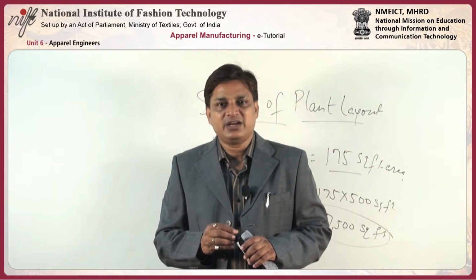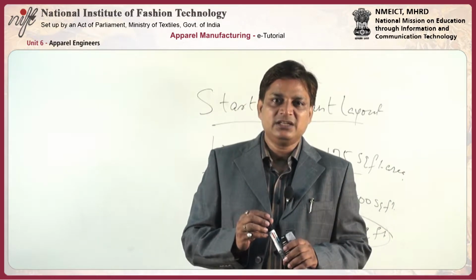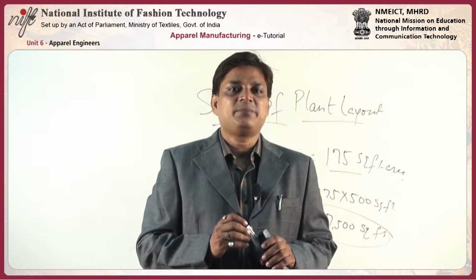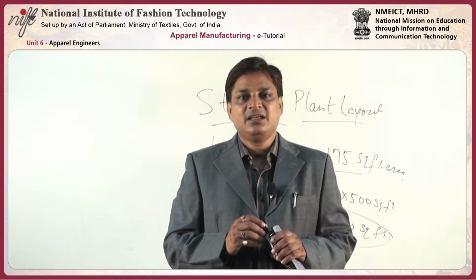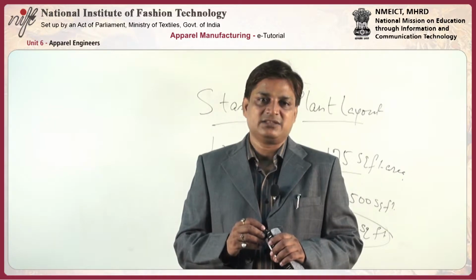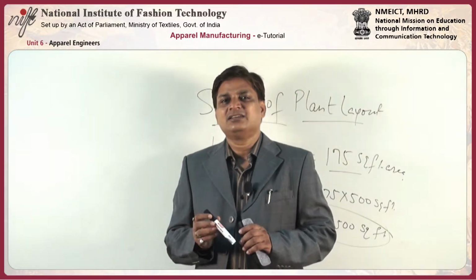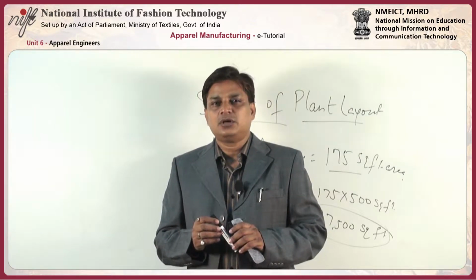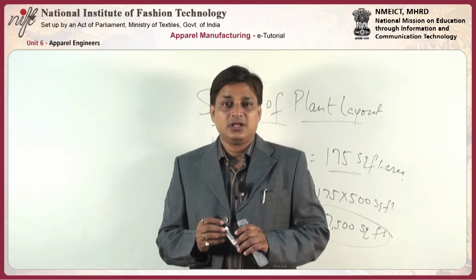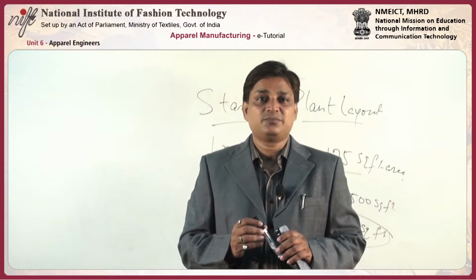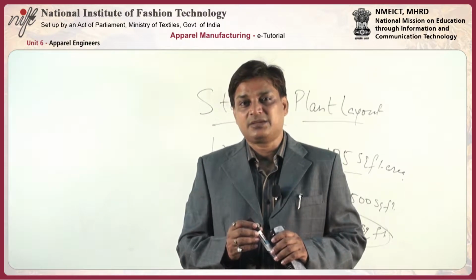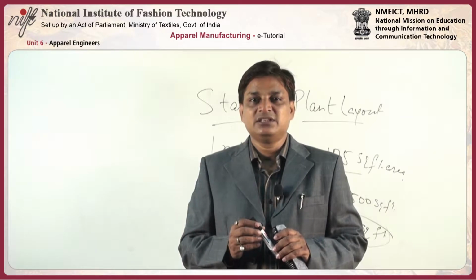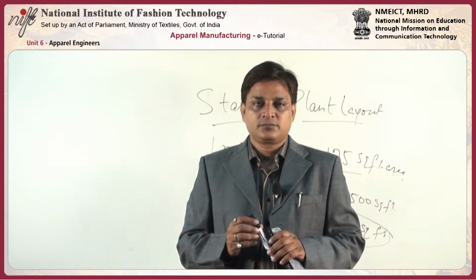Now, we will take the operation bulletin and zero down the SAM of the basic shirt. The next step is to reach the optimum output per line at 100% efficiency after doing balancing. So let's see, it comes to around 800 shirts per 8 hours per line. Now to match the target output, we have to set 10 lines producing 800 shirts per 8 hours per line. Further, it will also give the number of operators, helpers, line feeders, supervisors and QC to run the line.